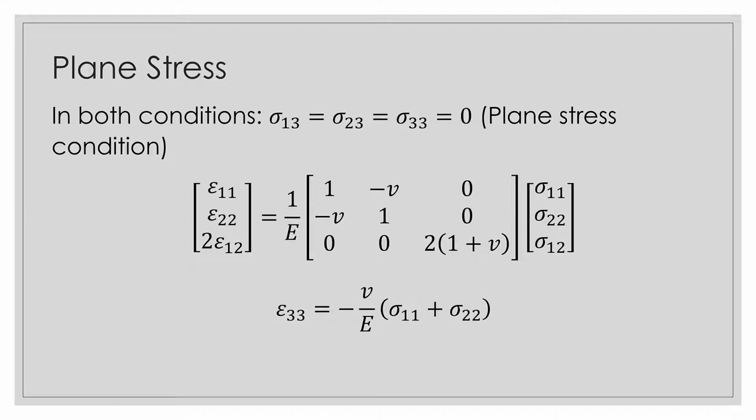So that concludes the theory, guys. As you may know by now, pipelines or pipes, tanks, are not too bad. Very simple to do, very simple to calculate, all because sigma 33 is equal to 0, and we can use plane stress. So let's jump into the examples where we can actually start to see this in action.